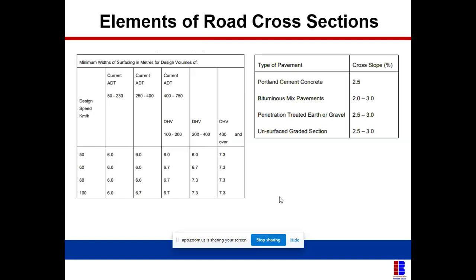When they were doing the earthwork and laying the asphalt, the surveyor didn't properly take a proper level in considering this 2.5% camber on the road. So that's why in some places you see water gathering on the road, which is bad. In more distant time, there will be seepage of water, leading to alligator cracks and all on the road. So the road will start giving way. So all these criteria need to be met as well.